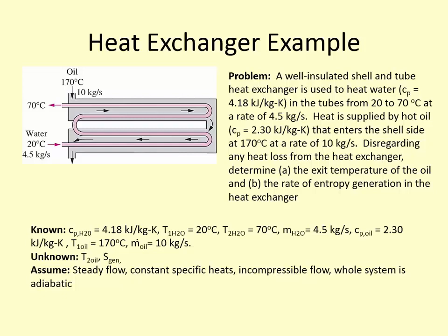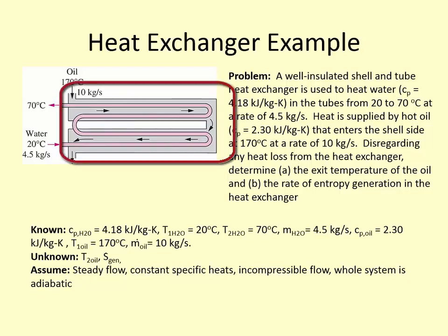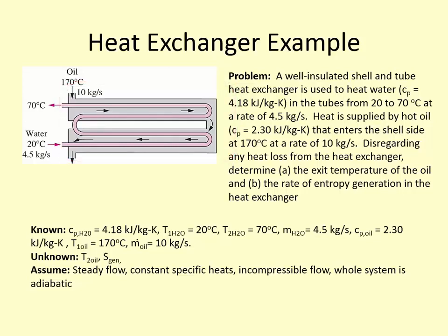Where's our system boundary? Right? So we've got some box with mass flowing into it and out of it. And then we've got this other thing with mass flowing in and out. So this is my system. Do I have mass flow crossing my boundaries? Yes, right? Do I have heat transfer crossing my boundaries? No. Okay, so you have to be careful when you analyze these problems that just because you solved for heat transfer previously doesn't mean you now need to plug it into this problem. Yes, if you're solving for the entropy generation of the fluid. Not if you're looking at it for the whole heat exchanger.